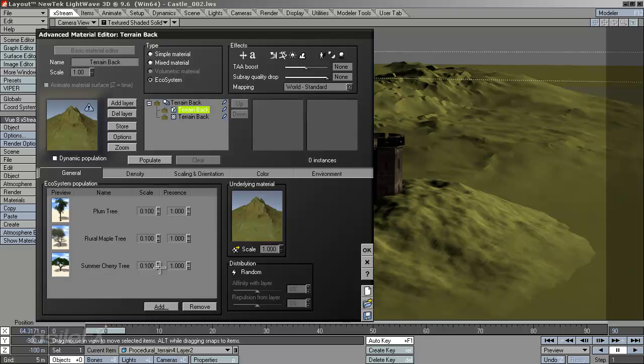Hopefully we don't run into any problems with it. Mostly it's for close-ups that it has UV mapping problems, but sometimes it has a tendency to change the overall colors to black and render all the plants black. So the scale, because the view unit of 1 is equal to 1 meter, is set to 0.1. If the internal unit was 0.1, I'm pretty sure it would set the scale to 1. That's a very recent change to the way that all of the units are working.